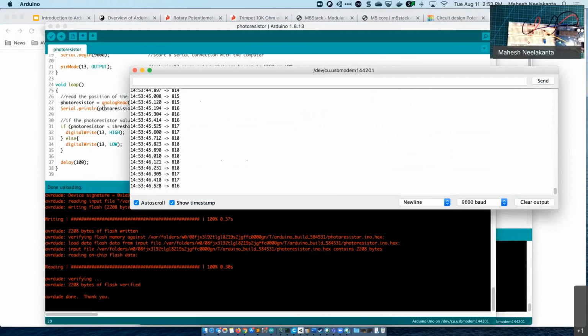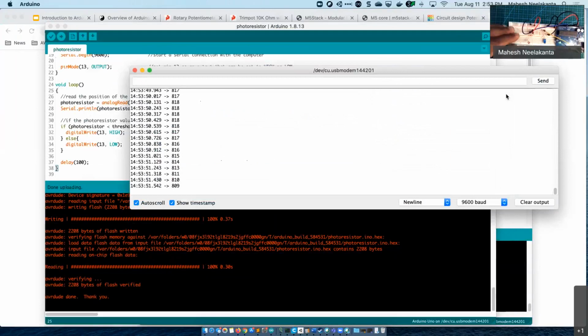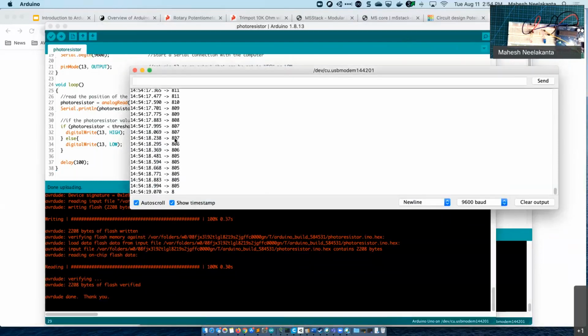So for example, I'm purposely going to make a mistake. I am going to disconnect my photoresistor. See that value? It's printing 0 all the time. And so if I put my photoresistor back in, hopefully in the right ports, the value comes back in. Okay, so without the debug information, that would have been really hard to figure out. So knowing how to print into your serial port and see what these values are is really, really important.